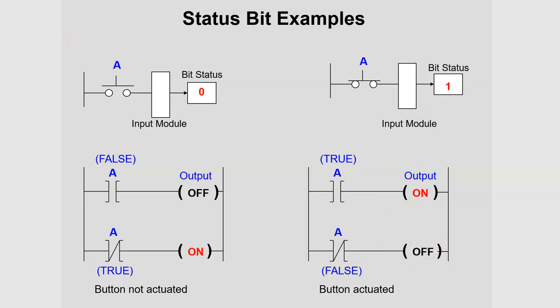So I would mark this slide. If you understand this one slide here, then you understand the operation of the examine if open and examine if closed instruction, and you'll do well with your programming.